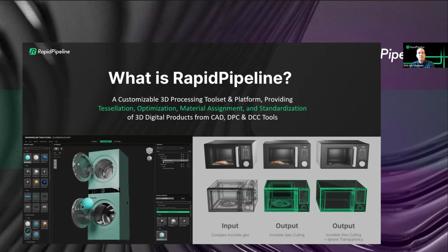And you look at the wireframe, there's engine parts inside of there that are necessary for manufacturing to have that data, but you don't really want that in your render model because, first of all, it's hidden. So it's not being rendered anyway, and it's just extra weight for the model. But also, when you're going downstream pipelines, you don't want to share your manufacturing know-how with other clients and your real-time models and all those things. So it's best just to call that out.